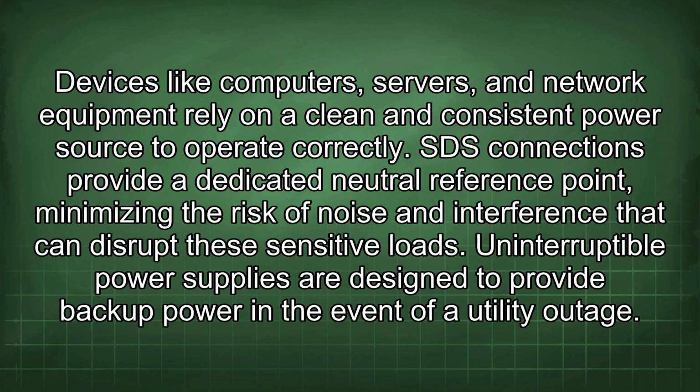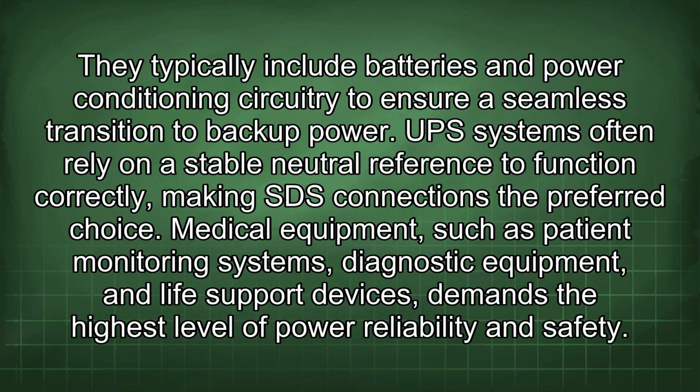SDS connections provide a dedicated neutral reference point, minimizing the risk of noise and interference that can disrupt these sensitive loads. Uninterruptible power supplies are designed to provide backup power in the event of a utility outage. They typically include batteries and power conditioning circuitry to ensure a seamless transition to backup power. UPS systems often rely on a stable neutral reference to function correctly, making SDS connections the preferred choice.